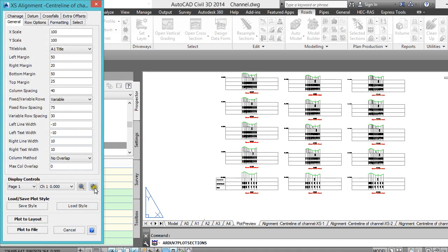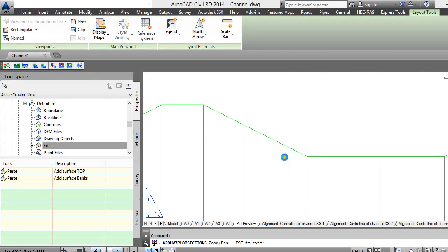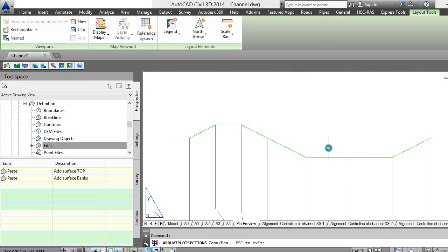Okay, as you can see here, let me zoom in. So you can see a 2-in-1 slope here, and I created up to here. I had earlier created a pitch line on here. I then offset it by 0.6, raised by 0.3, offset it by 0.6, offset it by 0.6, lowered it down by 0.3.